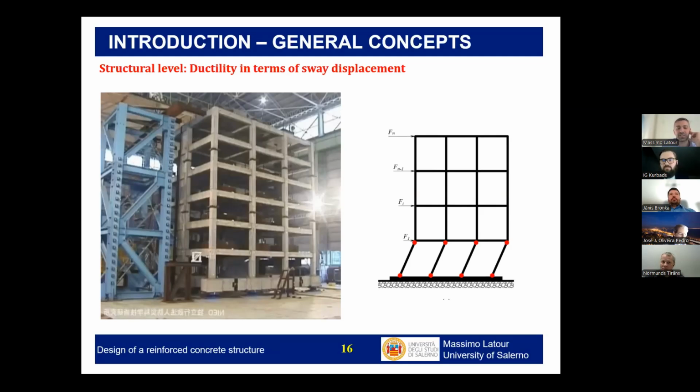How will the design be affected? In no way, because we usually don't consider the soil. Of course, in theory, there is a big problem of soil structure interaction, especially when you have piles, because piles are in part also damping some of the energy. So there is some kind of damping related to the pile and the interaction of the pile with the soil. But this is totally neglected because normally we always design with full restraint. So for the superstructure, there is no problem. The design will be the same independently from the type of foundation.